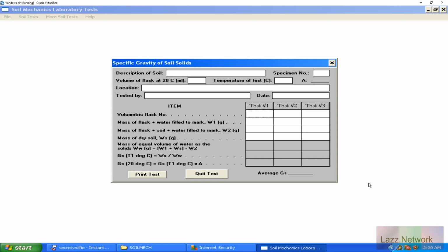So there's a scribe mark in the neck itself, and it's up to the laboratory and/or the technician calibrating your pycnometer to determine the meniscus line, because you can calibrate it from the bottom of the meniscus or the top of the meniscus, which, remember, the meniscus is the curvature of water.